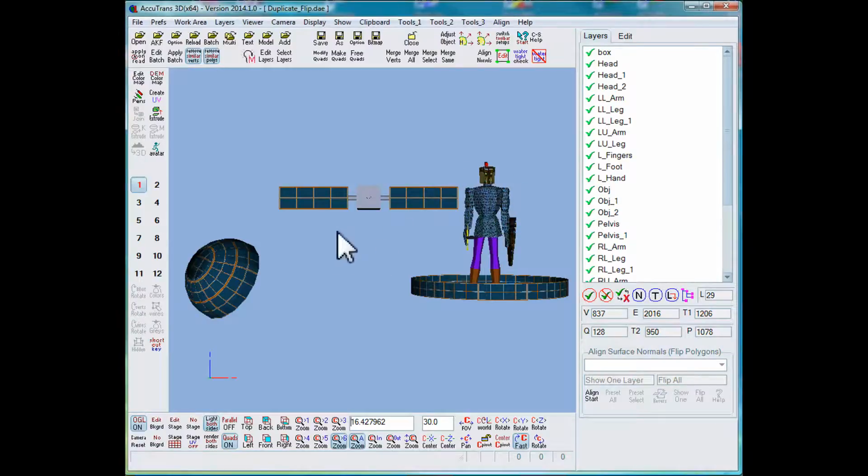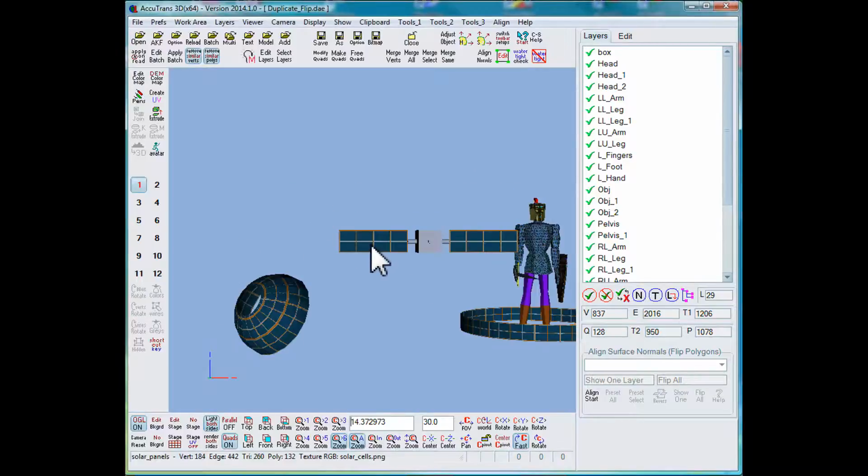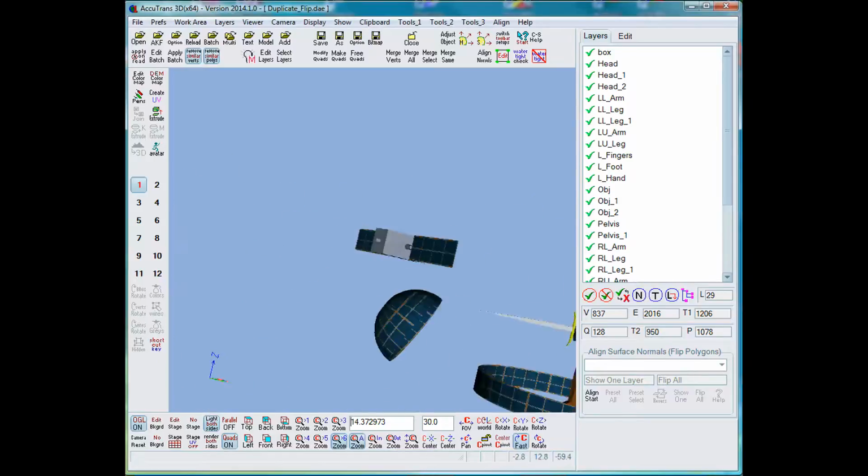So now another feature is to position the point on the model where the camera is going to look at. I'll position the cursor here, click the middle mouse button, and the camera is now pointed at this position, and when we revolve the camera it will keep looking at that position.